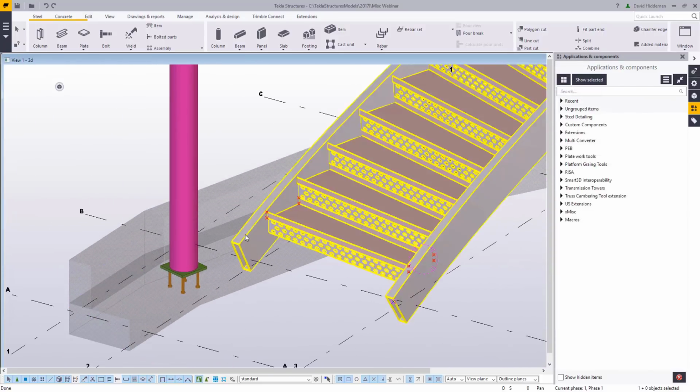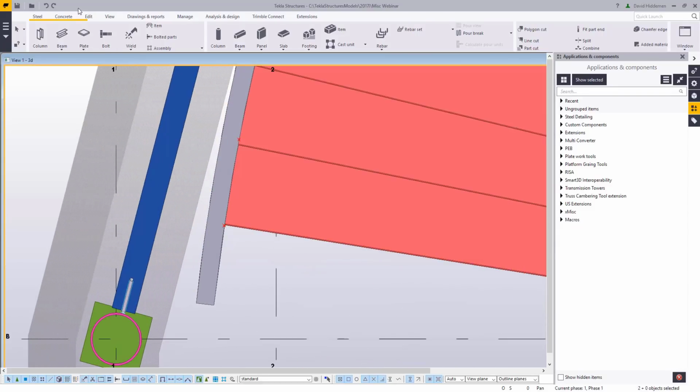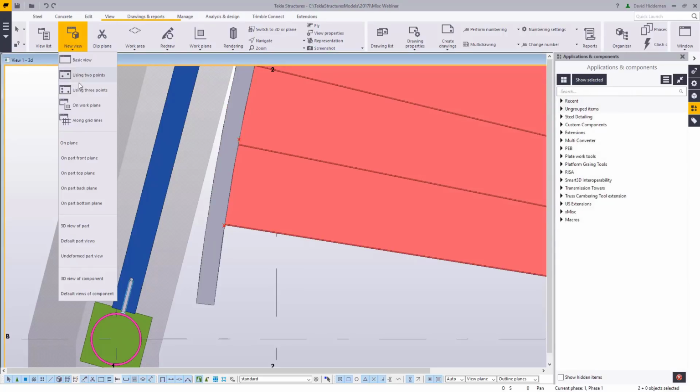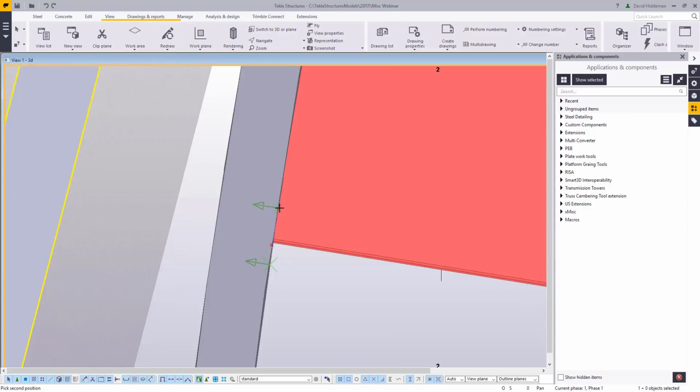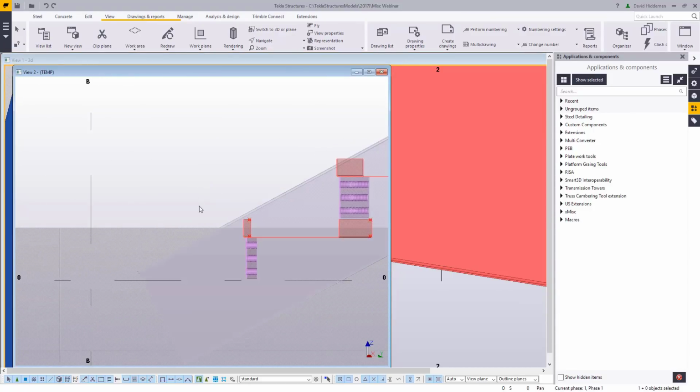Now, unfortunately, for the spiral material, the spiral stringer, because of the complex geometry, our default tools to cut and shape that will not work. But that just means it gives me another opportunity to switch to a manual mode. So I'll go ahead and cut myself a temporary view at that location. And then I'll just cut this stringer.